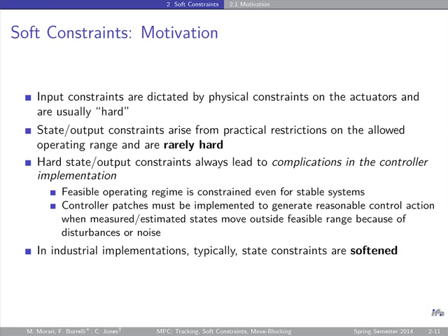You can make the constraints on the outputs, like here, time varying, and several of you asked me earlier today, can the constraints be time varying? Yes, they can be time varying. This is indicated by that k here, the maximum and minimum can be time varying. Obviously, some things you have to obey for this to make sense. For example, you don't want the control to continue and not look at the output, so the horizon nu has to be less than the horizon ny.